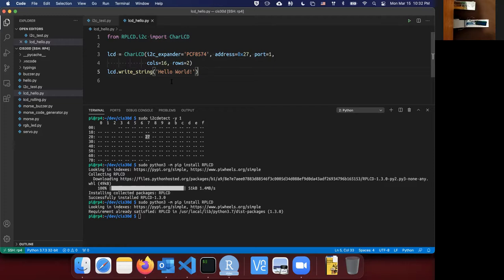Let me step back and talk about this library. This library makes it super easy to deal with the LCD. Underlying this, it uses the I2C protocol. Actually, in this case, it's using the SMBus subset of I2C to communicate. There are a lot of lower level function calls to handle the actual protocol, remember that data transfer chart I showed you with the timing and the pulses.